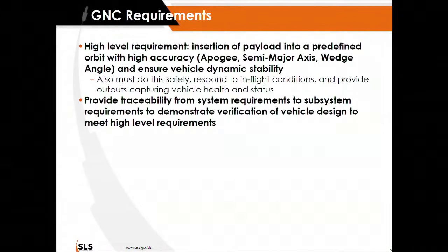So that's our main metric that we always have to assess against in our simulations, and it also ties into when we do some of the SIL testing, integrated testing, and hardware in the loop, how we compare back to what our results are, what our performance is from the GNC perspective. So from that, we have to go all the way from the vehicle spec down to our modeling and simulation, to the flight software, and fully close the loops on our verification objectives. We have to show that our sims work and also that the hardware works as well, and there are no unintended effects.